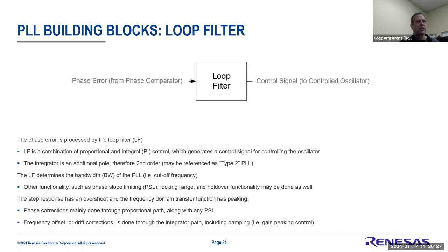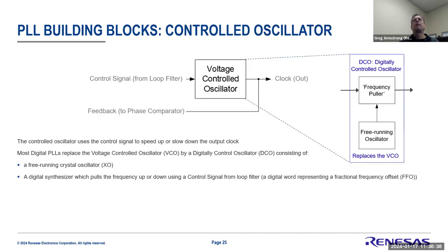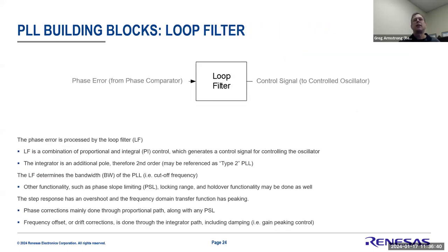So if that phase changed at all, like all of a sudden 10 nanoseconds occurred, that 10 is going to spit out fairly quickly coming out of the loop filter. But if I want to open up my window and average over a very long component of time, that's almost like lowering your bandwidth to maybe 1 hertz or 1 millihertz. I want a very long window of measurement, and over that very long window, I'll output the average to the control circuit.